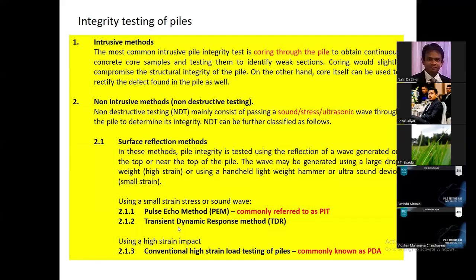The transient dynamic response method is not very common. It is an advanced version of the pulse echo method. Then comes the conventional high strain dynamic load test. This is commonly referred to as PDA. PDA refers to pile dynamic analyzer. This is a commercial name given for a testing procedure, but the technical term is high strain dynamic load test. I would like to discuss the high strain dynamic load test as well.